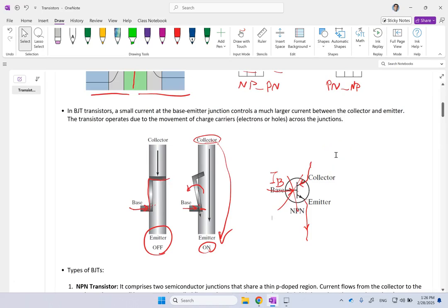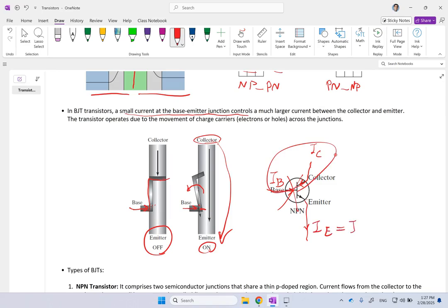Okay, so first of all, they are what we call current-based valves or switches, because everything is controlled through the current, the small current that is sent through the base. And then I of the base and I of the collector come together, and they are added together and become I of the emitter. So I of the emitter is going to be I of the base plus I of the collector, because that acts like a junction. But again, whether this opens or closes depends on the value of the base here.